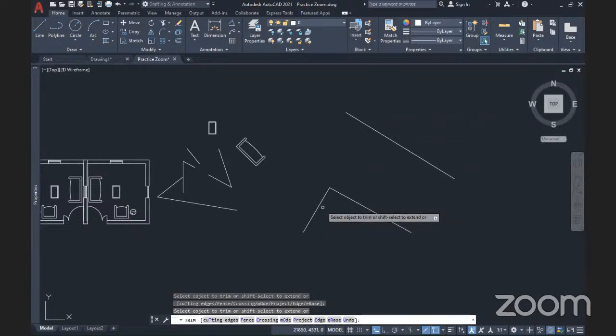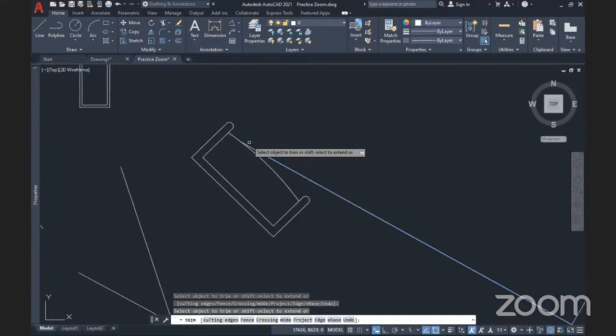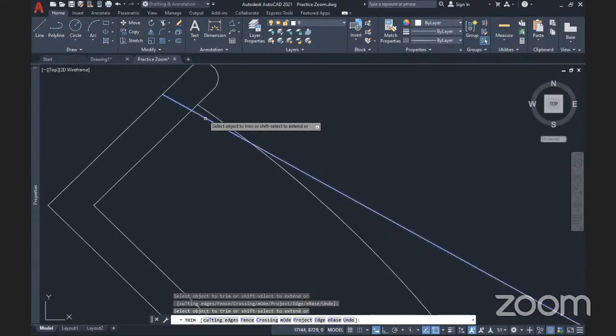So now what you do, you just hold down shift and click on the line you want to extend. Hold down shift in this case and click on that line. I can hold down shift again. Okay, it does not extend anywhere. Let's see. Okay, yes, it extends actually. So I can hold down shift, click, hold down shift, click to the next boundary.